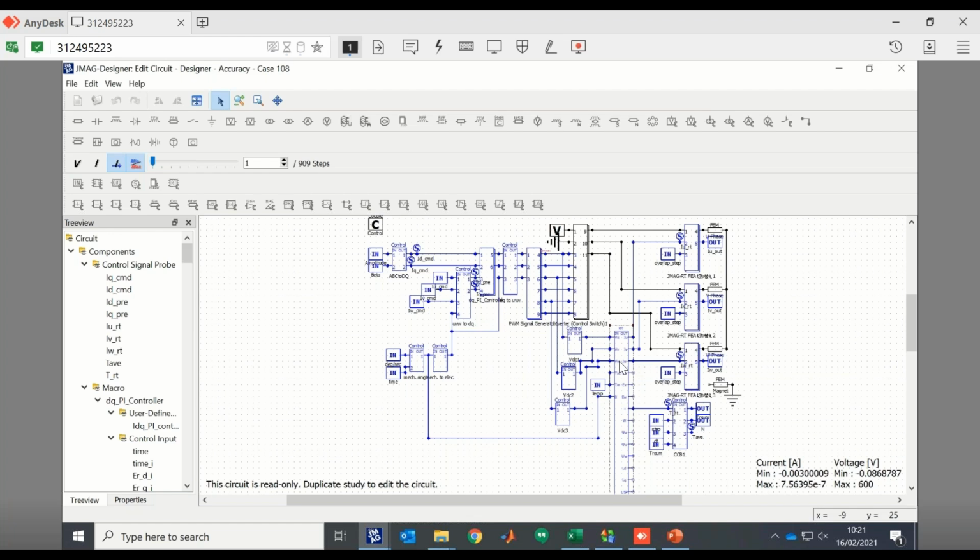And what I'm doing here is, first, for the initial transient period, I'm calculating using JMAG-RT. And once I reach a certain tolerance, or I reach a bit of steady state, I have my motor here, and I can move on to my FEA simulation with it. That's why in this graph you saw a bit of a straight line. I'm going to show it again. The straight line in the beginning, and then it moves on to the normal curve that we're expecting.